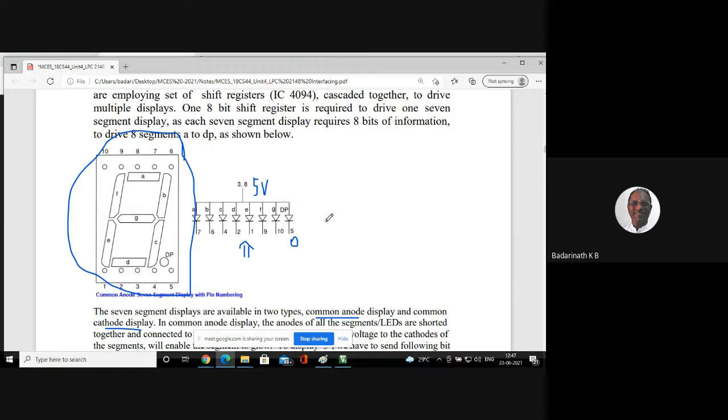Now, let's learn how to prepare the byte. One byte of information is required to make one digit glow. These digits are capable of displaying numerals and also alphabets, which is why we also call them alphanumeric displays. But there is limited capability for displaying alphabets. Compared to the LED, now we are migrating to the 7-segment digit. A 7-segment digit is far better than a normal LED because you can represent numbers and also alphabets. By properly choosing the segments to glow, you can make the whole digit look like a number or a limited set of alphabets.